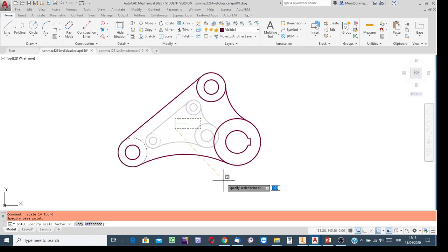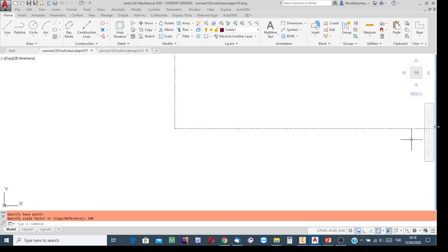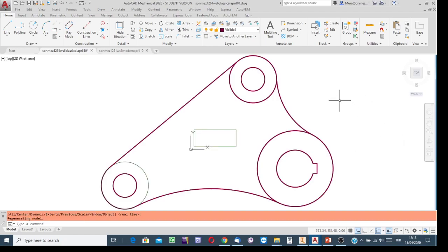And then into this box, write the scale factor. I said 100 times, for instance, and then press enter. That is it. Remember, this is just an example from the content of the previous class time or the corresponding video record. Now this projection is 100 times bigger.